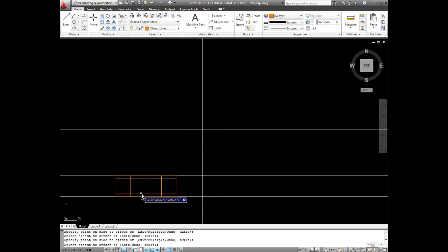That will be the body of our object from here to here. And now we're going to use a chamfer tool. The distance is going to be 0.125. The second distance will be 0.125 also. We're going to choose multiple. We're going to put one here, one on this corner, and one on this corner.